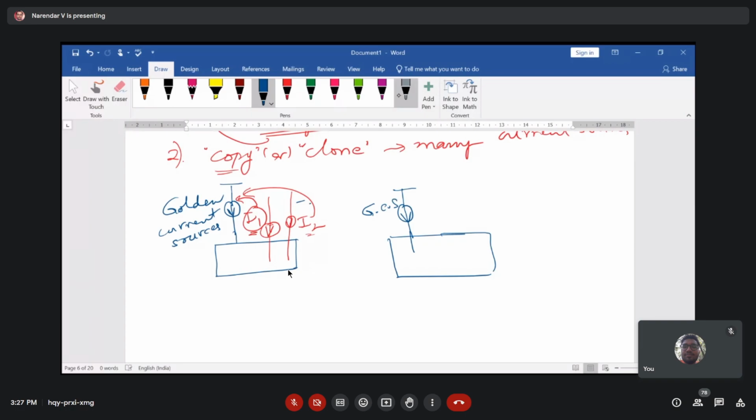Now we just take a MOS transistor here, connected to ground, and here it generates a current called I1. So this I1 current is generated from your band gap circuitry current, and so this current is independent of all the problems that we are talking about.